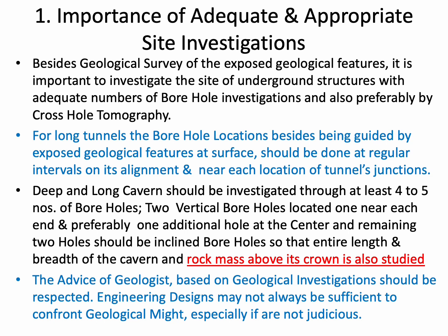First point is the importance of adequate and appropriate site investigations. Besides geological survey of the exposed geological features, it is important to investigate the site of underground structures with adequate numbers of borehole investigations, and also preferably by cross-hole tomography. For long tunnels, the borehole locations, besides being guided by exposed geological features at the surface, should be at regular intervals on its alignment and near each location of tunnel junctions.